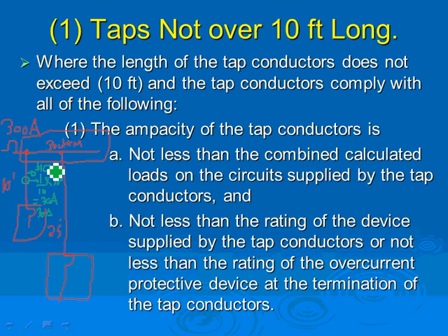That could be 2 15 amp breakers, yes. That could be 2 breakers or 3 breakers, 10, 10, 10. Good point. That circuit breaker can be 3 breakers, 10 amps each, or 1 breaker, 30 amps, as long as you limit it to the ampacity of the conductor. Good point. Or fused. Now, moving into the circuit breaker, moving into the 30, now this is the 25 feet.